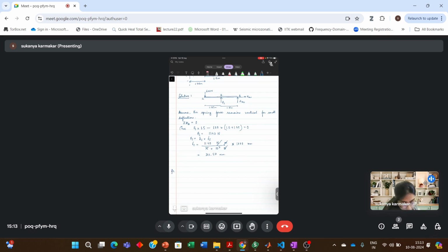So here you have a 2.5 meter diameter sound baffle. Basically, you have a disc and it weighs 1.1 kilonewton, and it is to be hung from a ceiling with three springs which are mounted on radii, making an angle of 120 degrees with each other. Each of the springs is 250 long. There are three springs A, B, and C. Springs A and B have a spring constant of 14 kilonewton per meter, and C has a spring constant of 16 kilonewton per meter. First, let me draw the setup.